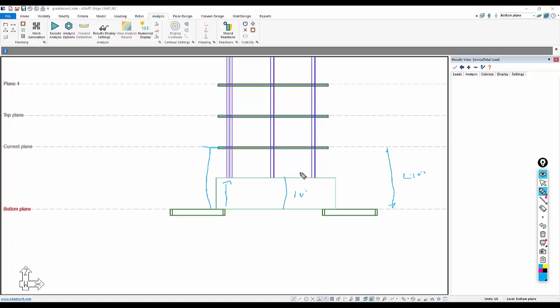So if you needed to simulate, for example, the load transfer through more points other than just these three, then we might have to put in a series of columns to represent better distribution of force down into the beam versus just some discrete points where we have the columns modeled. We have the beam here. Let's go and take a look at that beam.